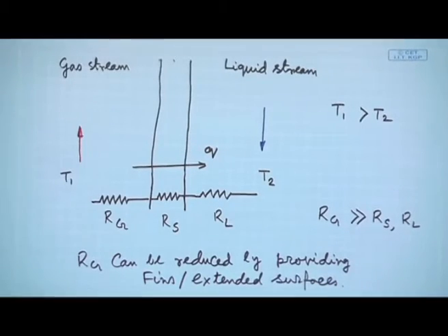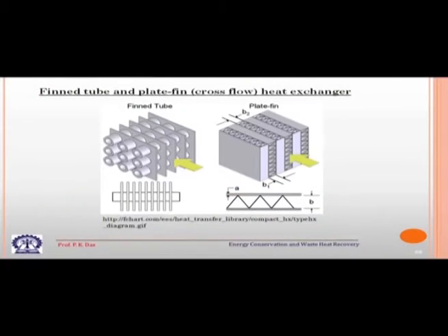This is a very common device for increasing the gas side rate of heat transfer, and we can have in tubular geometry the fin tube type of heat exchanger, and in plane geometry we can have the plate fin type of heat exchanger, and I can very quickly describe them.